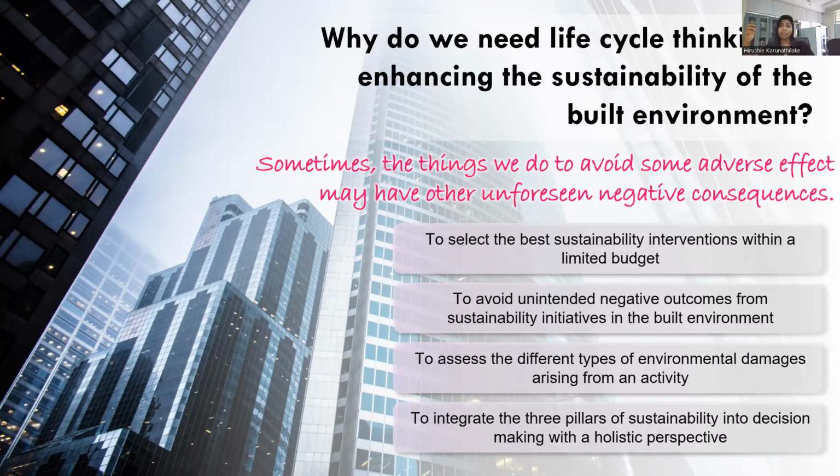But when we conducted a life cycle assessment on this, we found that this leads to an increase in the ozone depletion impact category. Higher levels of ozone depletion damage could be seen when we do this assessment. When investigating the possible root cause, it was identified that this insulation material, when it is disposed of or when it degrades, releases emissions that are damaging to the ozone layer, like chlorofluorocarbons. These are ozone depleting. So while we are trying to achieve an improvement on one side by reducing greenhouse gas emissions, we are having this unintended negative consequence of higher levels of ozone depletion.